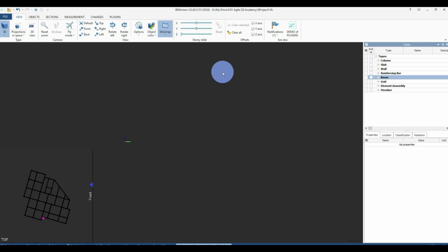If you extract the volume without recognizing this, you might get the volume of steel structures as part of it. If you have steel columns and concrete columns, and you just say, model, give me the volume of the columns, you might get the volume of concrete and steel all together. That's why it's very good to first understand the components of the model. Then you can go to the BIM quantity extractions from the IFC model after you understand what it contains.